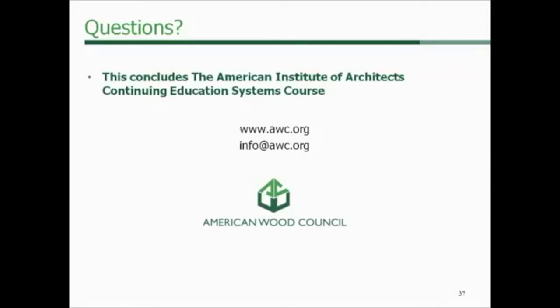But the goal was to be more flexible, more user-friendly. So a couple of things did change, like I mentioned, the U factors and the R values aligned a little bit better. But probably if I had to say the single biggest change was there's a new compliance path, which is known as the ERI path, or the Energy Rated Index path. What it does is it allows something like a HERS score to be used to show compliance for the IECC. But it should be noted that it does have a backstop that you can't go past. I think it's the 2009 IECC envelope provisions.